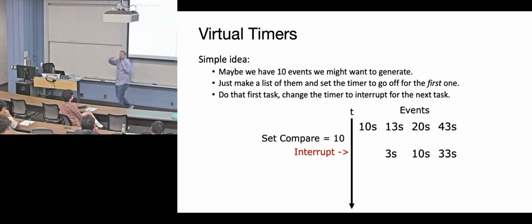And so you're keeping this list of all the current state of the timers, when their goals are, and whenever you enter that loop, you're going to decrement by how long you've set your hardware timer for. So again, we go through, what are we going to set our timer for this time?